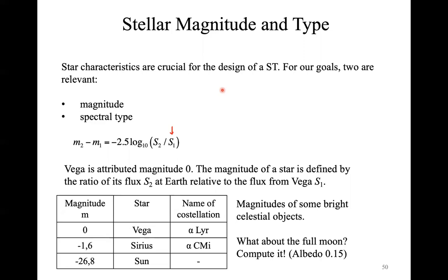So if you have, for example, star trackers, you use them to determine the orientation of the spacecraft at the instant at which you are collecting the measurement from the star tracker. The QUEST algorithm is probably the best approach because, as I told you, if you have multiple observations, you are able to weigh those observations.